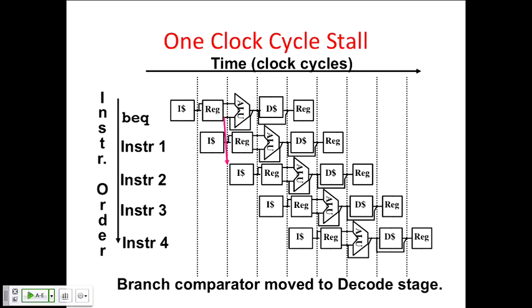Well, the other nice thing about the way this pipeline and the instruction set were designed is I don't actually update any state till I get to the end, or at least the memory stage. So provided I can find out before these instructions write to memory or the register file, I can just blow them away and nothing will have happened. We designed the instruction set so all the updates happen at the end of the pipeline, and so there's no permanent change made until you get there.